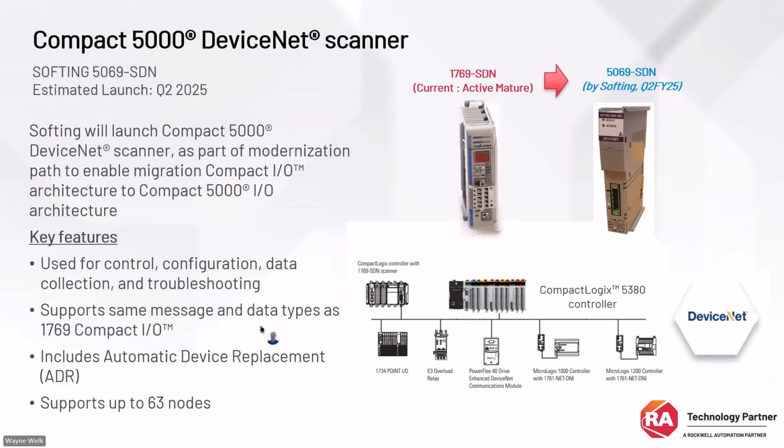Also, this is about the only time I'm really going to touch on hardware, because it helps with the migration part of it, because we have a lot of DeviceNet MCCs out there. A lot of times we might have had a CompactLogix, an L-series, or excuse me, a 1769 style. Well, Rockwell now has a DeviceNet scanner module for the 5380 CompactLogix.